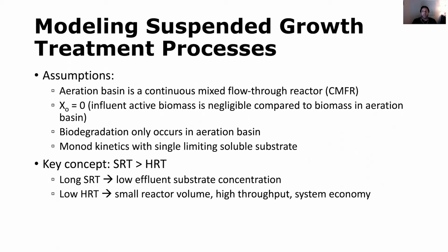So when we model the biomass, which we use the variable X for, when we model the biomass coming into the system, we can assume that that's negligible compared to what's growing within the system, so that it will be equal to 0. We'll assume that biodegradation, or the conversion of the carbon compounds, only occurs in the aeration basin. And we're also going to assume Monod kinetics with single limiting soluble substrate. And I'll get into detail in a couple minutes on what that means.